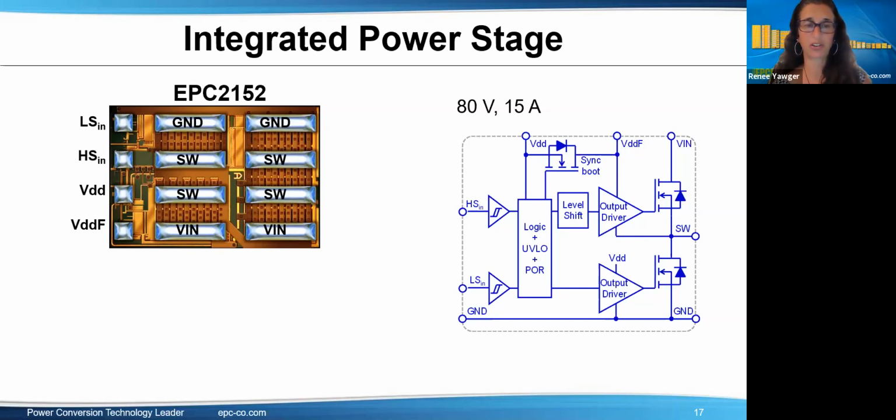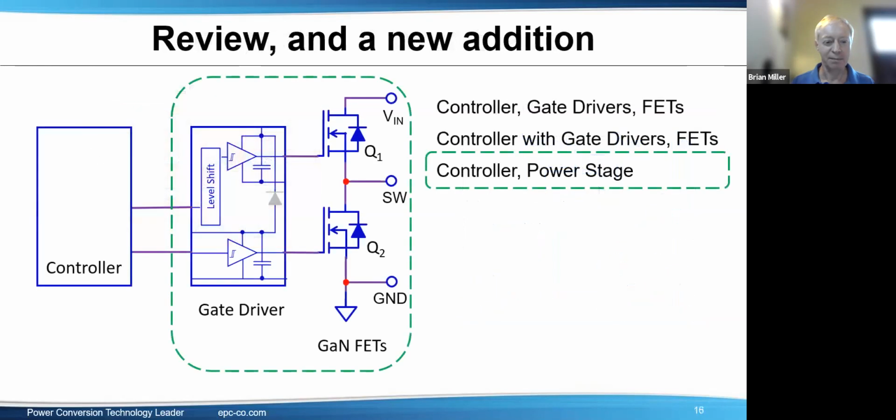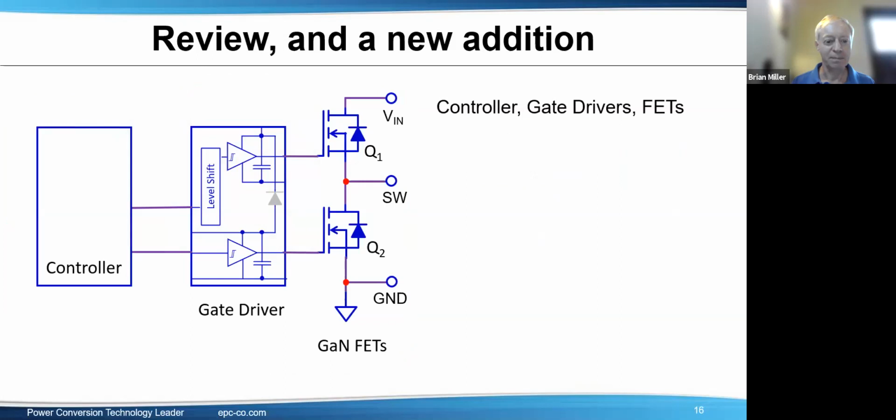What about additional external anti-parallel diodes? Yeah, that's a good topic. Let me go back up to some of the GaN drivers. If you have a gate driver that's built for GaN FETs, the switch node will come in here, and the GaN gate driver will know that you could have a low voltage that comes in, and it can take that. So there's no particular need for a parallel diode.